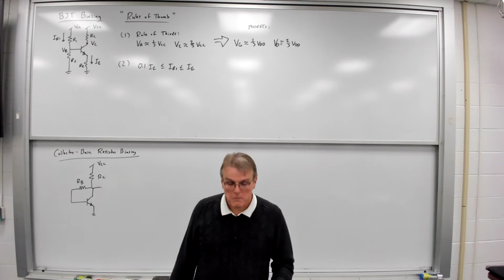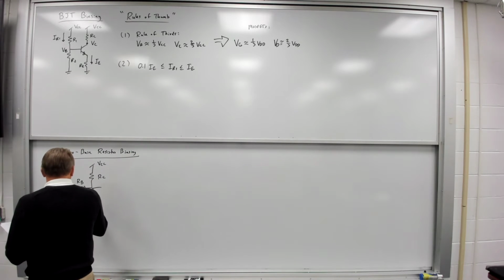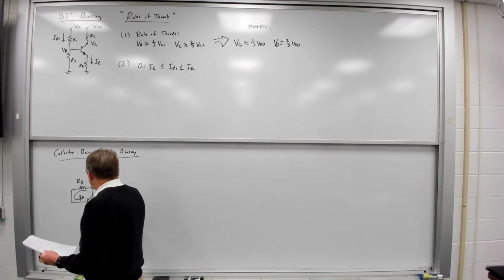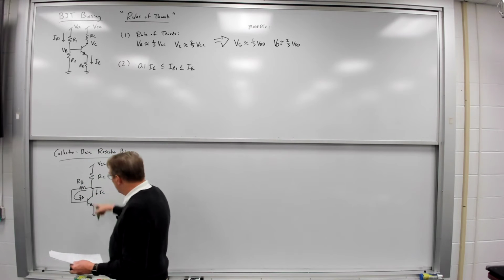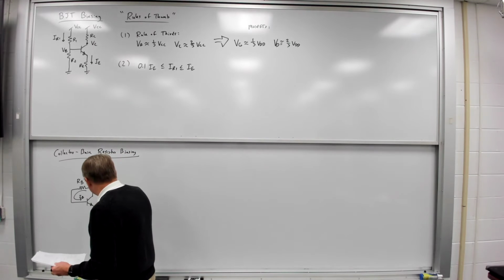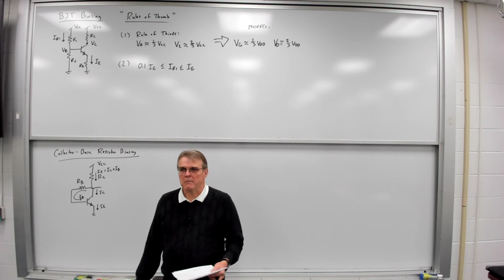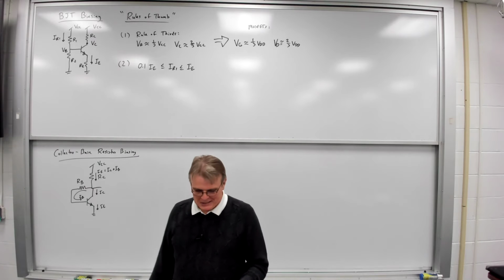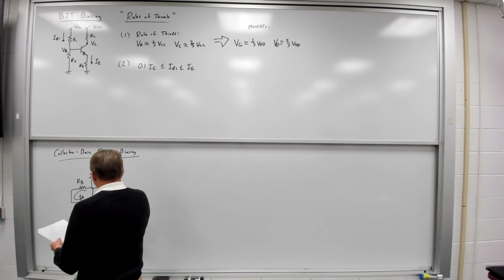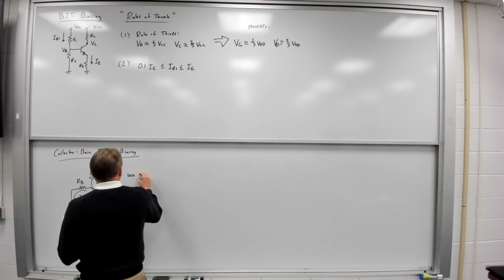be equal to 0. There is a base current you have to account for that's going to flow into the base. And so this will be the collector current. So the current through the resistor will actually be equal to the emitter current, because IE is equal to IC plus IB. So this current and the emitter current are going to be the same thing when you think about it. KCL dictates that.